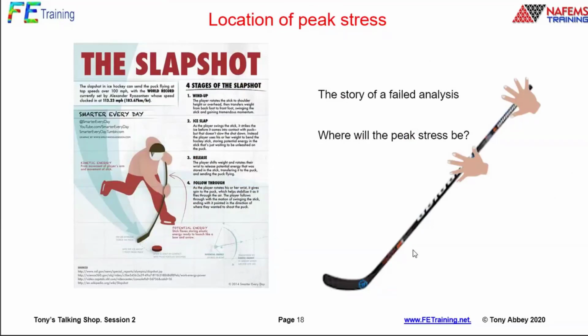Cut a long story short, we submitted this to the company. The managing director loved the opposition's result because he said, well, on test, that's where we get a failure right there. And we were kind of puzzled. I phoned up the technical director and said, well, what's going on here? He said, well, we didn't tell you there's actually a splice in there. So the splice generates the stress concentration. And that's actually a fabrication failure at that particular point. But none of you knew that.